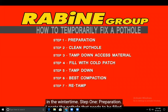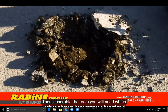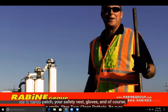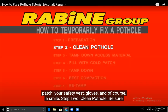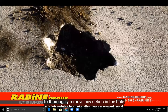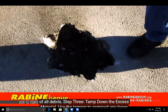Step 1. Preparation. Locate the pothole that needs to be filled. Then assemble the tools you will need, which include a broom, hand tamper, a bag of cold patch, your safety vest, gloves, and of course, a smile. Step 2. Clean pothole. Be sure to thoroughly remove any debris in the hole, which might include dirt, loose gravel, and asphalt. Next, sweep around the edges to make sure that the surrounding ledge is clear of all debris.